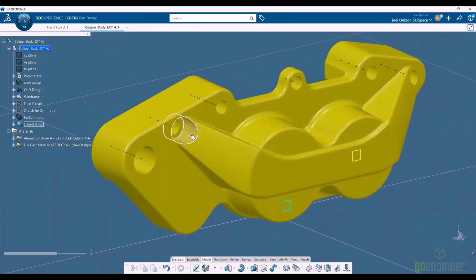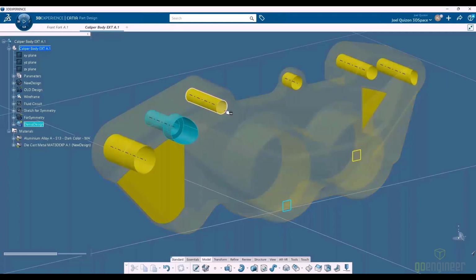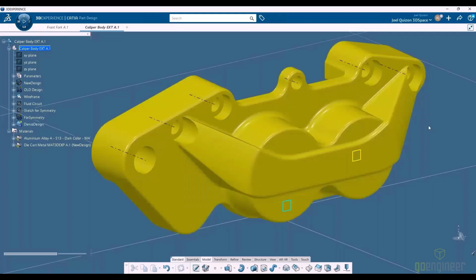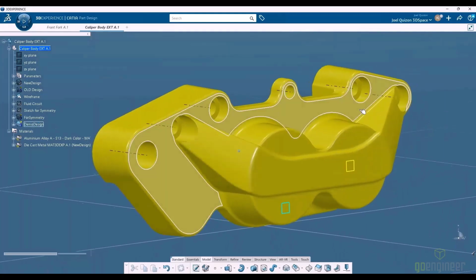The nice thing, this is a really great tool. If I realize I want to make some other ones the same, it's called Semantic Painter. So I just click on the feature, go to Semantic Painter. Now I'm able to go in, it shows what similar features are, and I start picking the ones I want to change to that. And basically it's a copy, right? Copying that into here.